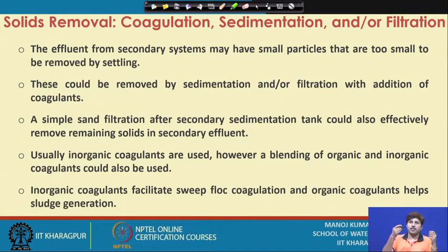One, at the primary sedimentation system, apart from the grit and the screens. The screens remove floating materials, and grit removes a lot of inorganic solids. But in the main treatment chain, the primary sedimentation removes a large portion of the suspended materials, whether they are organic or inorganic, and then there is the secondary settling unit or secondary clarifier, what we typically call the secondary sedimentation tank.